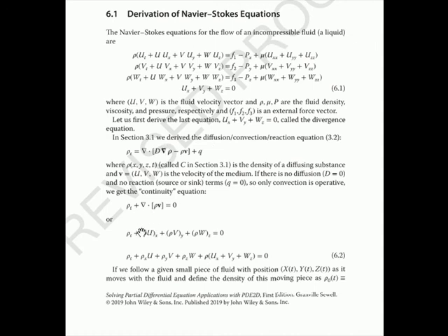So you expand that out and you get, well, divergence means derivative with respect to x of the first component. Well, the velocity field now is u, v, w. That's the fluid velocity. We're talking about the density of the fluid, but it's moving with the fluid with velocity u, v, and w. So V is the field u, v, w. So we multiply that by rho and take the divergence.